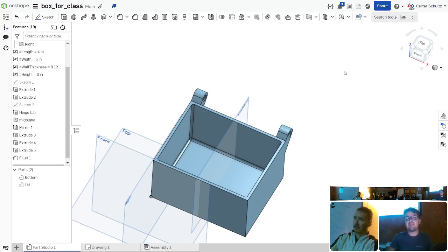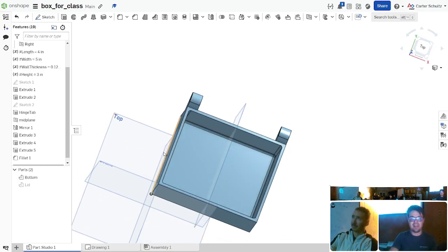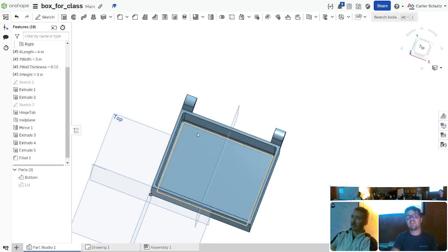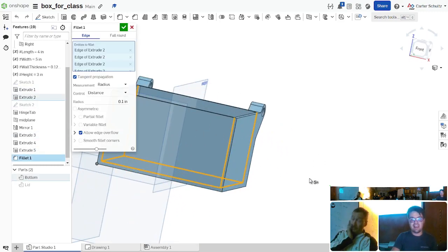One of the ways that I keep myself from having to deal with clicking hell, of re-clicking a bunch of edges to make the fillets look good, is by not doing the fillets on the full model of the part. For this particular part, this part is not only symmetric about this plane, but it's symmetric a lot of ways about this plane. I would have done the fillets on just 1/4 of it and then symmetric mirrored them both times, so I just have fewer edges to click. The earlier I do the fillets before I do a bunch of mirroring stuff, the more they'll generalize and the less hell I have to click when I go in here and just click everything.